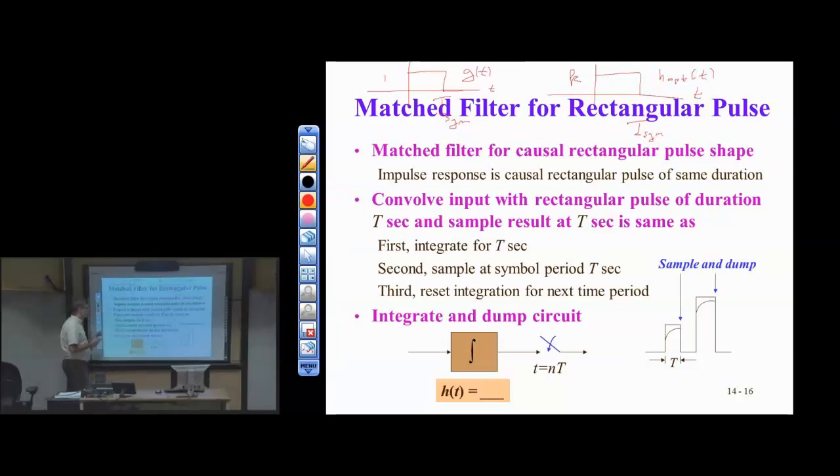Normally we would have in our receiver the matched filter, followed by a sampling operation at the symbol time. That is to say, we'll do something over one symbol period. We'll take the result at the end of that symbol period and compare it against 0 if it's 2-PAM. We do this at the end of every symbol period to estimate what bit or bit pattern had been transmitted.